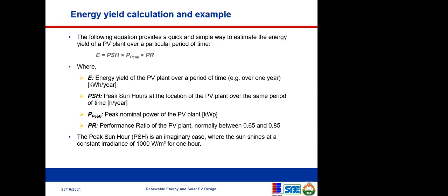So I just want to be sure. That's not what it will give you. It will give you 32 over 10, 3.2 hours. That's what you will get. It's 400 times 8 divided by 1,000. 400 irradiance multiplied by 8 hours divided by 1,000 irradiance. It will give you a time of 3.2 hours.